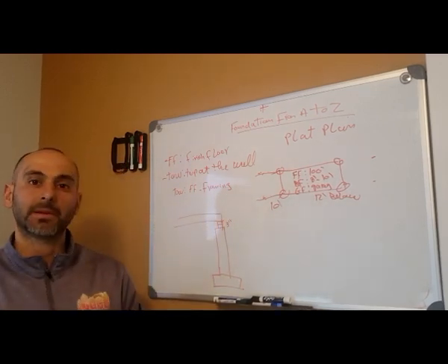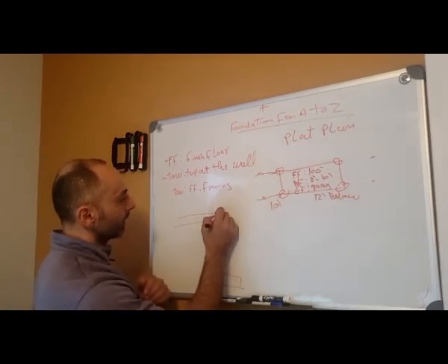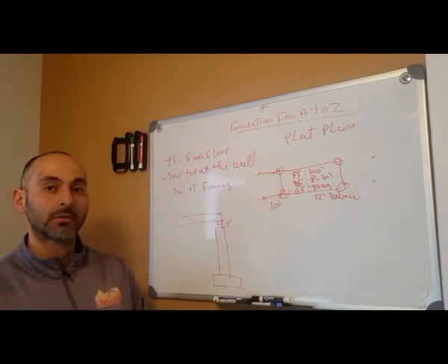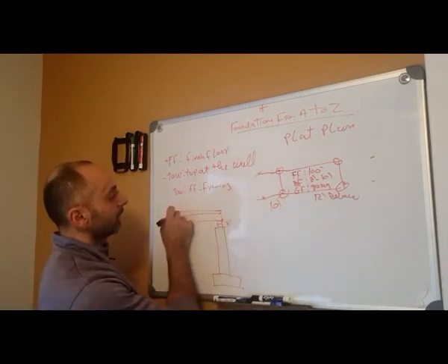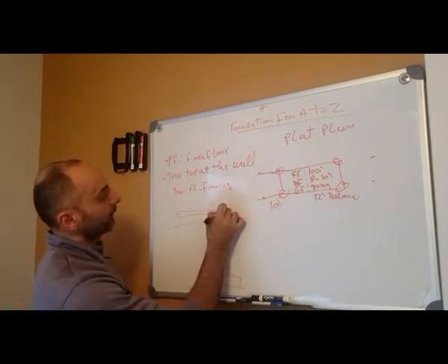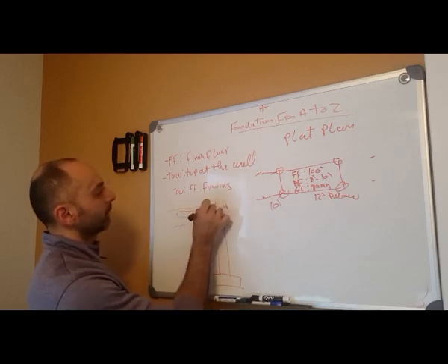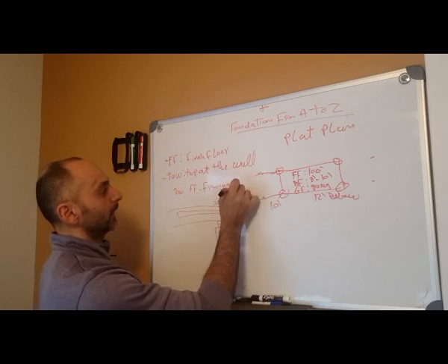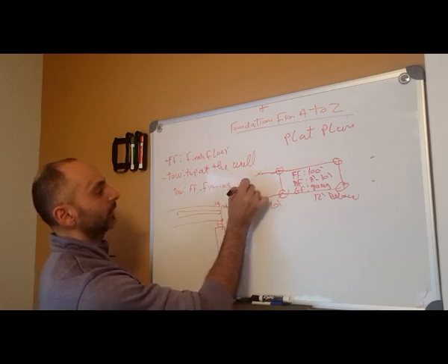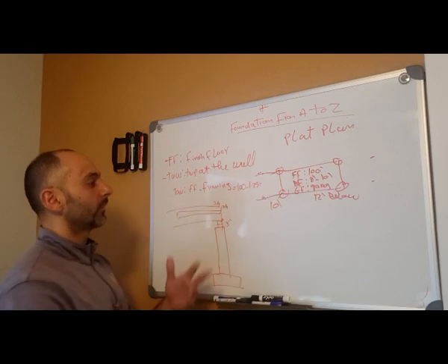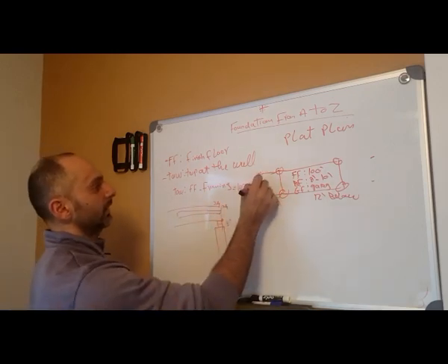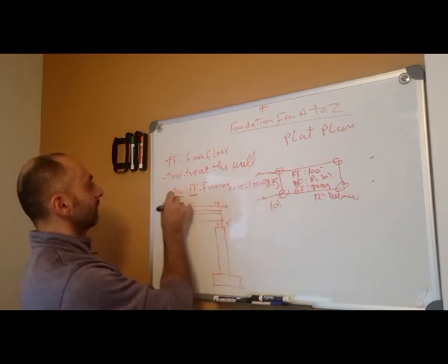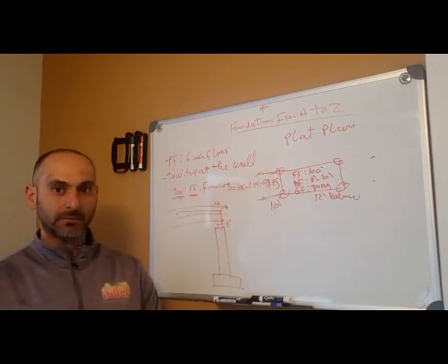Find out from your framing plans what the height of your framing is. Then you have the subfloor, which is 3/4, then the finish, another 3/4 if it's wood. So you're looking at about 15 inches. So now if you're looking at 100 minus 1.25, which is the engineer's measure for 15 inches, it's going to be 98.75. So your top of the wall is 98.75.